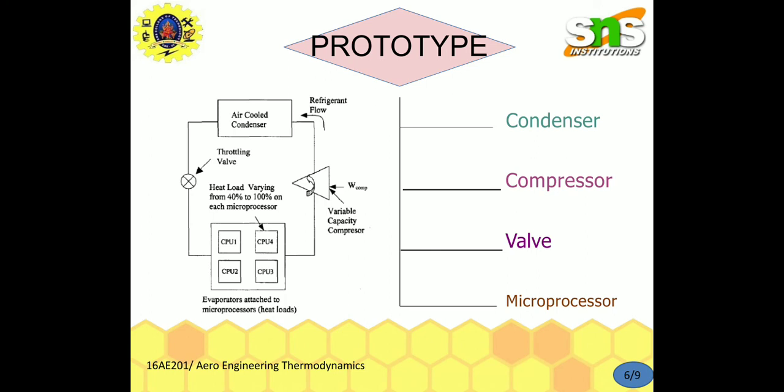In the early years of the 20th century, the vapor absorption cycle using a water-ammonia system was popular and widely used. But after the development of the vapor compression cycle, it lost much of its importance because of its low coefficient of performance, about one-fifth of that of the vapor compression cycle. Nowadays, the vapor absorption cycle is used only where heat is more readily available than electricity, such as waste heat provided by solar collectors or refrigeration in recreational vehicles.